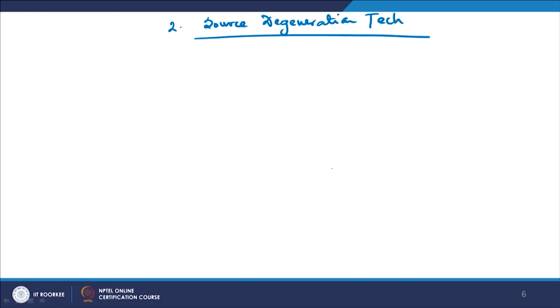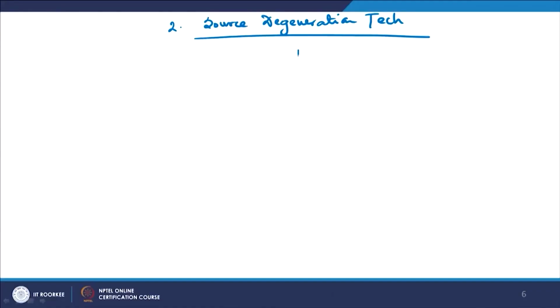So what I am trying to do is bias it from an external source, using a DC bias. I am doing it with an external source and trying to find out. Let me draw for you how it is different. It is exactly the same as the first case. The only thing is that here we are adding an extra source resistance in series with your RD and VDD.